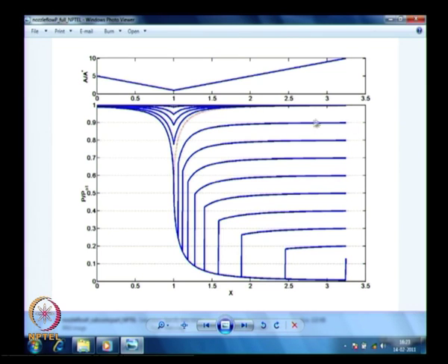After that, you can see what PB by P naught 1 I used, just directly from here. I used 0.9, 0.8, 0.7, 0.6, 0.5, 0.4, 0.3, 0.2, 0.1. Actually, I used this number slightly above 0.1. I think it was 0.13 or something for this particular nozzle, gamma equal to 1.4 case. That is the second critical pressure.